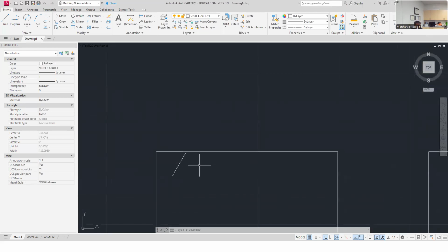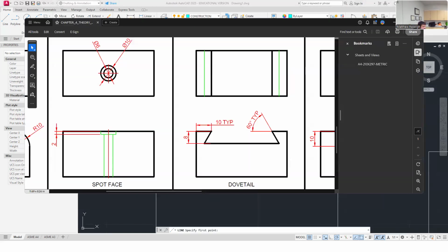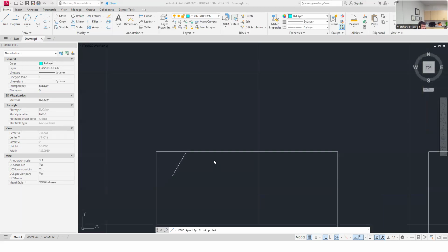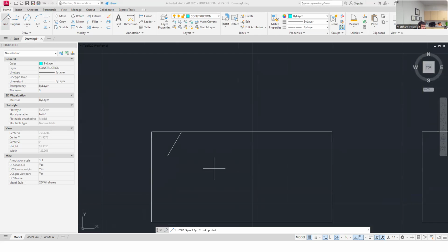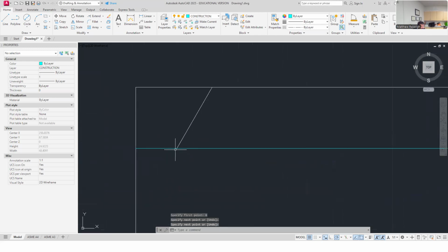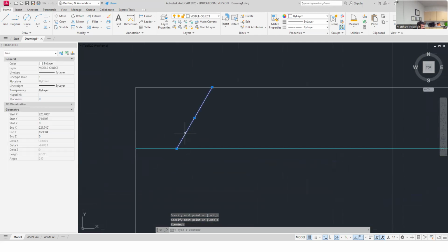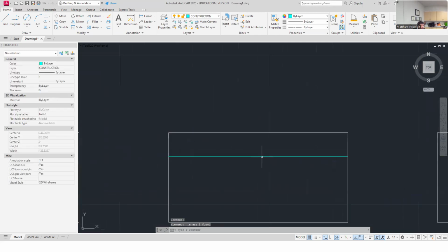I left that long. What I could do is I could have had a construction line in here, and then I could have put that across at 8 millimeter here. Like I could have done this preemptively and said 8 millimeter down, draw across as a construction line. That's how far down that needed to go. So in the event that I hadn't drawn this yet and I had planned on needing to know how deep it goes,